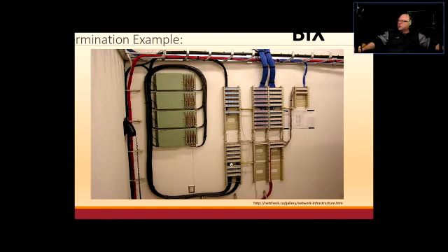They're terminated here, and maybe the field wiring is terminated also on another BIX field. All right. So now this is terminated on that. Remember, we punch them from the front, and then we flip it upside down. So the terminated wires are on the back end of the connector, and the slots that are free to grab those pairs from the front are at the front. And we do the same thing with the field wiring. And then we use something that's called a cross-connect wire.